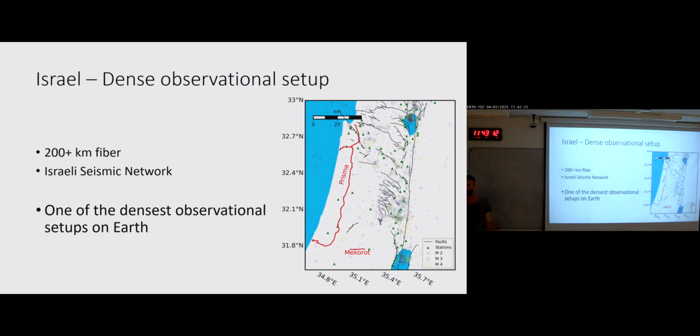You said something about how you calibrate. I'm assuming there's need for calibration to get the strain rate from the optical signal. Yeah, so what we actually measure is phase rate. And there is a simple linear equation that considers the refraction index of the fiber and also a few optical parameters, but it's fairly constant, like the conversion between phase rate and strain rate. There is a problem with saturation because you measure phase, which is between minus pi and pi. So if you measure very strong deformations, you need to unwrap the phase. And this is something that is problematic for early warning, where you're interested in very high amplitude signals, and still something that people are working on. But it's basically analytical. Yeah, it's analytical. But they can also measure it. They can apply a stretcher that actually stretches the fiber by a known amount and calibrate it empirically.